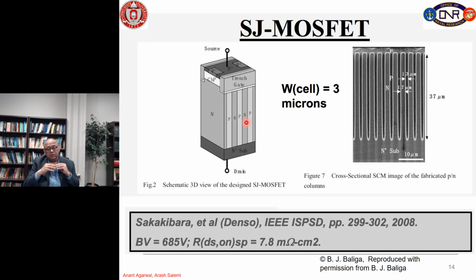In silicon carbide we still have not been able to make it. So in silicon, essentially, if we were doing a planar DMOSFET structure, we will probably stop at 400-500 volts. But since we can do superjunction structure, which has a much lower R on, because we can dope the N-type pillars very heavily, we can now make these devices up to 900 volts.